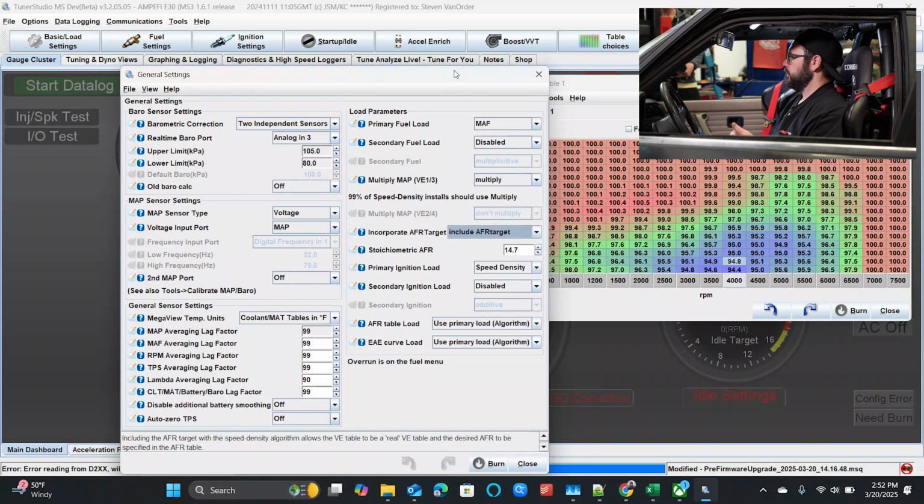I know that's a real number, and on a production engine, generally the OEMs are going to leave some performance on the table for emissions reasons, or whatever choices they made. It's not unheard of to have a maximum VE value on a pedestrian vehicle that only reaches 85 or 90, especially if it does not have a performance camshaft in it. That's pretty standard.